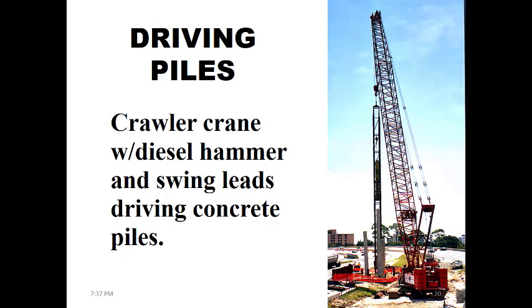If it happens in the first few seconds, then it might be possible to loosen it up and pull out the pile from its position. But if it's already driven enough for it to get stuck in there, then there is no way that the machine will be able to pull out a pile and drive another one.